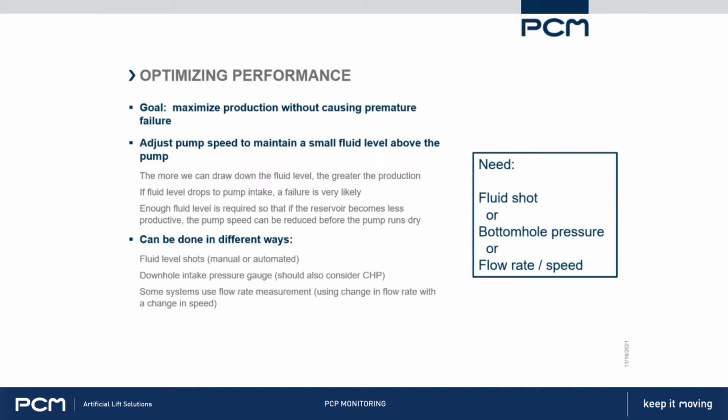On the other hand, if you see there's very little fluid above the pump, then you're going to slow the pump down. And again, you want to then do another fluid shot to see how much, have you slowed it down enough to be safe.